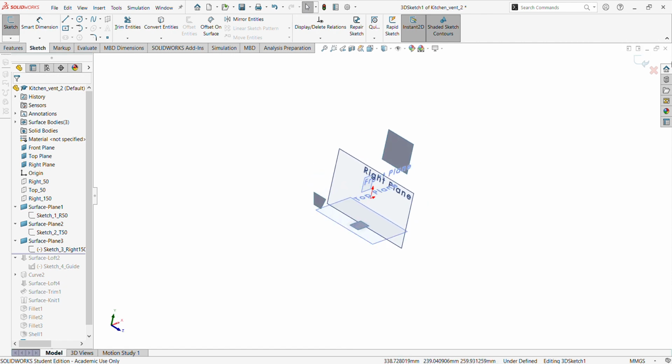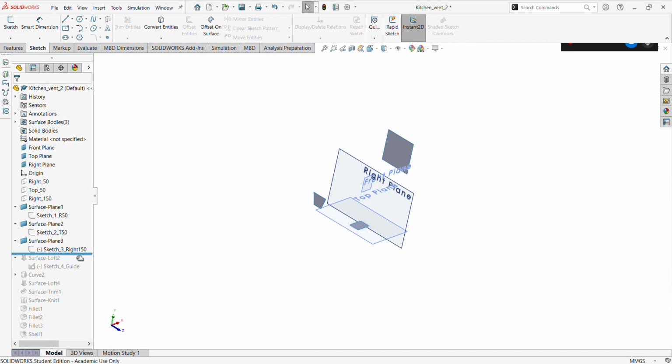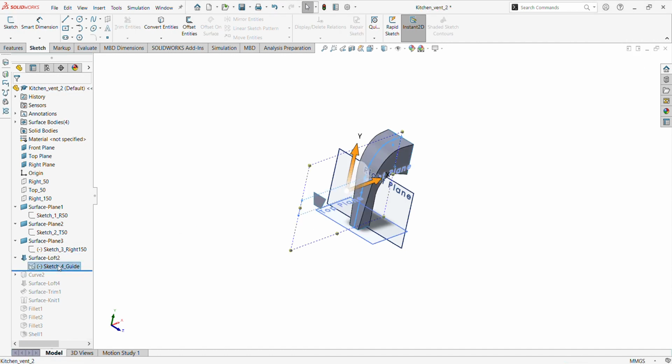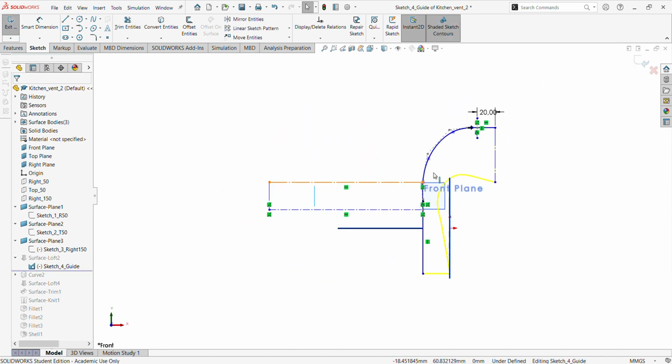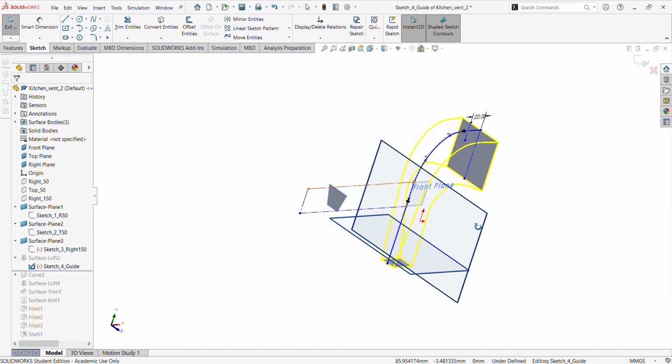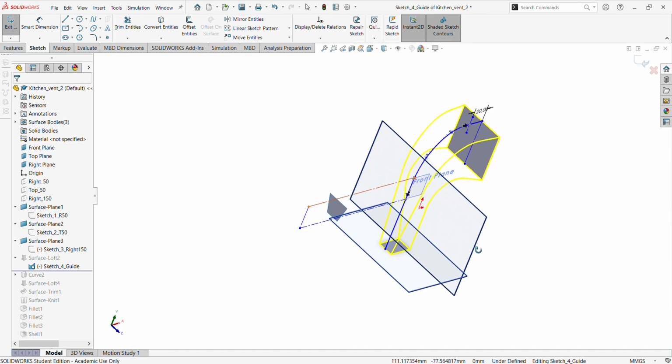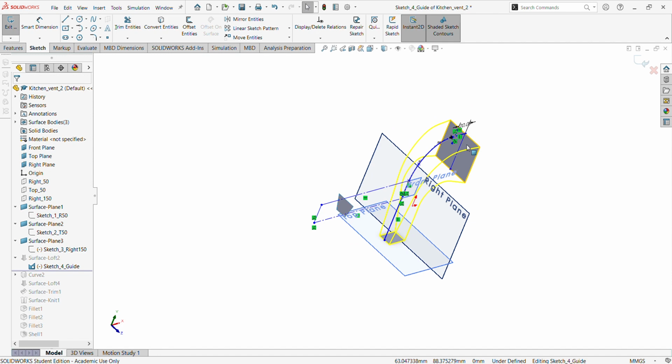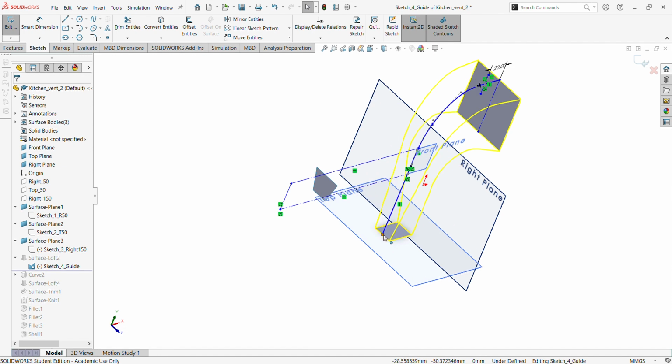Okay, but let's look at the sketch we have already done before for this. Let me see, I think I used, all right, that was a 2D sketch. So this was the first sketch. I used the 2D sketch, but you can also use, depends. I made it as simple as possible, because this surface and this surface are in alignment, so I could penetrate with just a 2D sketch from this surface to this surface. So this will now act as my guide curve.